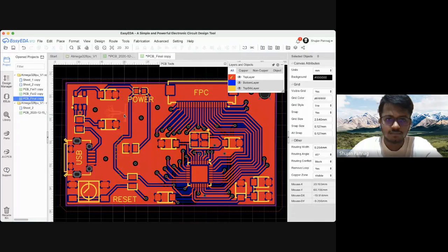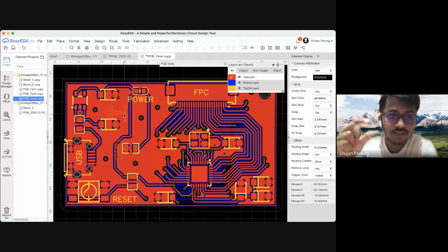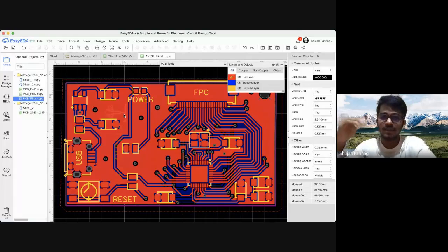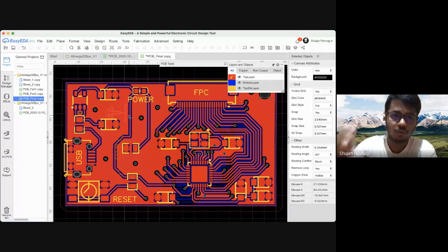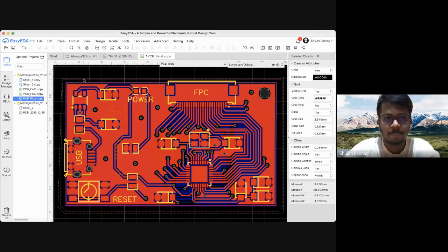When that is happening, you find a PCB whose fiberglass dielectric is very low, and then the price actually increases when you go too deep into reducing your noise in the circuitry. So basically, what I talked about was how to reduce noise, and some tools and tricks you can use in high speed PCBs.